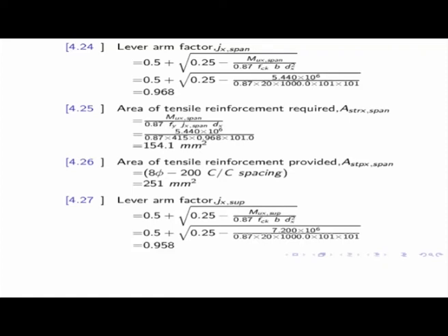So what I shall do now: I have checked the depth of the slab based on the maximum bending moment out of those four. We have four bending moments, in two different locations, one at the support and another at the span, and also in two different directions, along X and along Y. Out of that we have chosen the maximum one.